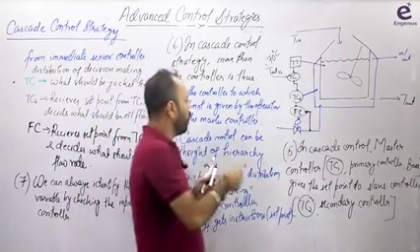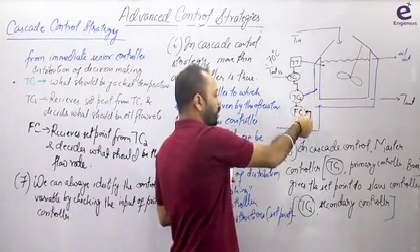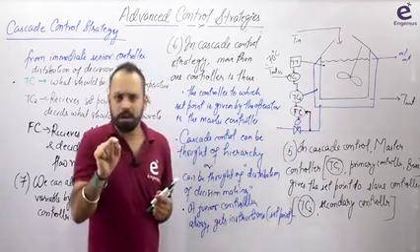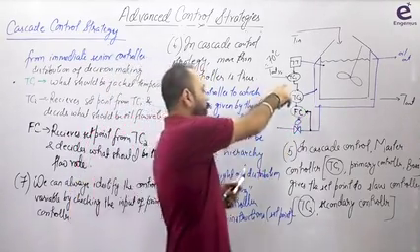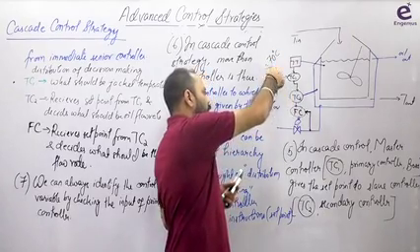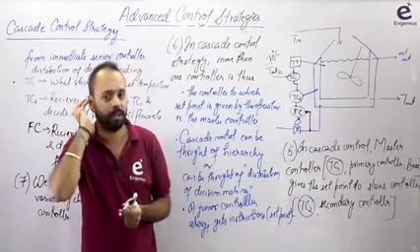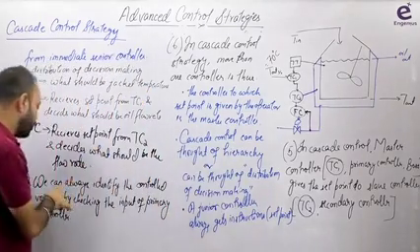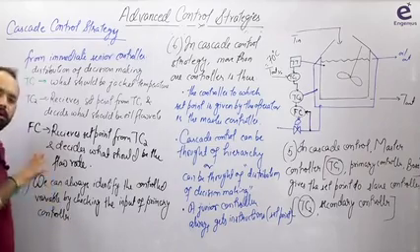Now you can see that here the set point is of jacket temperature. I am measuring jacket temperature. Here is the set point of the flow rate. I am measuring flow rate. So is flow rate the control variable? No. Jacket temperature control variable? No. See the TC1. TC1 को जो मैं set point दे रहा हूँ, this set point is for T out, means T out should be the control variable. So that's what I am writing here. We can always identify the control variable by checking the input of primary controller.